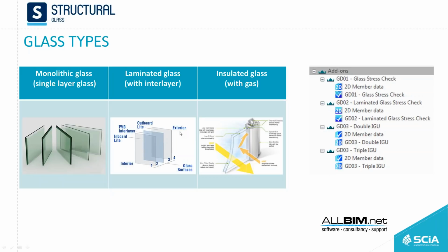The advantage is that we can get cracks in one of the layers and the others will survive. Another aspect is the load sharing, which is very different. The code will give us some idea of how to calculate the transfer of the loads from one layer to another. It's not straightforward. It actually depends on the load duration. According to that, the code has a simplified method in which we can calculate an equivalent effective thickness for stress and an effective thickness for deflections.